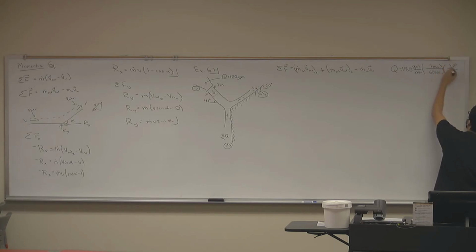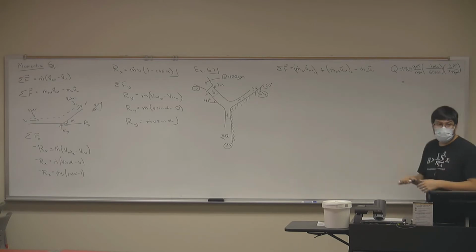You don't necessarily have to have these unit conversions memorized, at least not for this class, because our tests are all open book, open notes. But sometimes it's helpful to at least know how to convert the units, right? Good. So we notice that gallons cancels out, minutes cancels out, and we end up with how many cubic feet per second of flow, at least at the inlet.